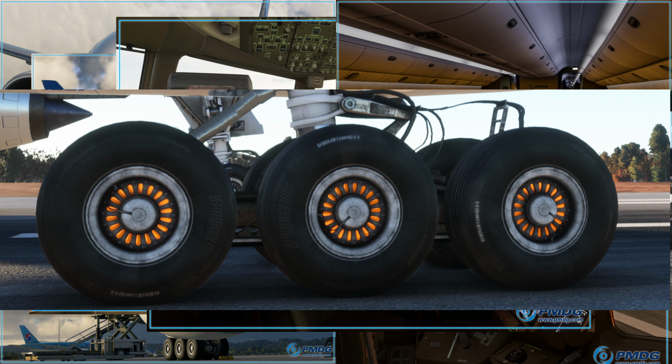Therefore, in order to normalize the feeling of the brakes for the pilot, the braking system only uses 4 brakes on each main landing gear during taxi. So one of the pair of wheels is not going to aid in the braking, and the system automatically decides which ones to use based on the brake temperature and a couple of further inputs that go right into it.